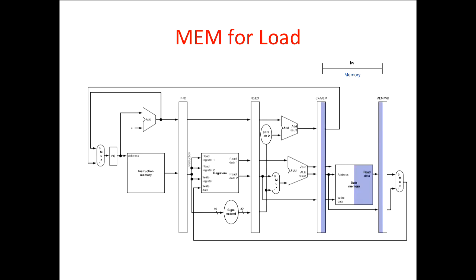Yep, Daniel? When you say it's a register, do you mean it stores only 32 bits? Yeah, good question. When we say register, it's a bit of a generic term. This is as many bits as you need to capture all those values. It's a set of flip-flops that are clocked, and they capture all those signals coming in and delay them until the start of the next clock cycle.